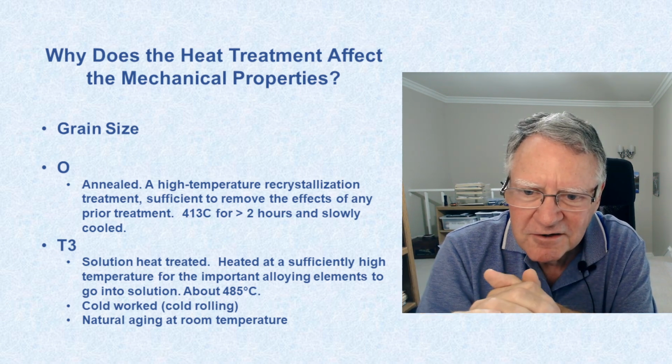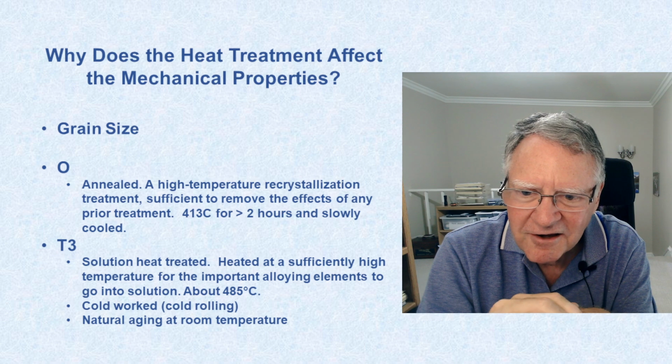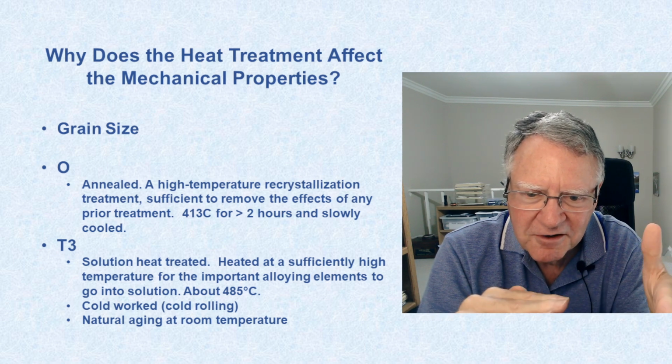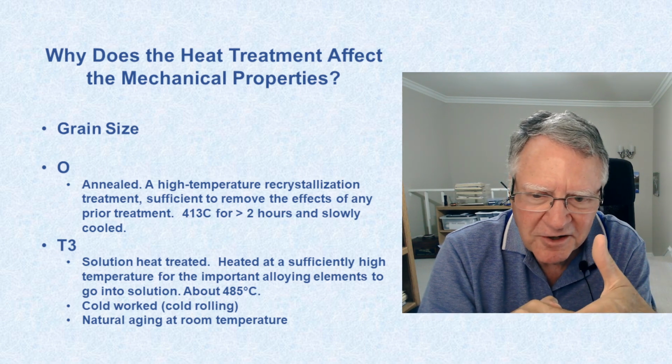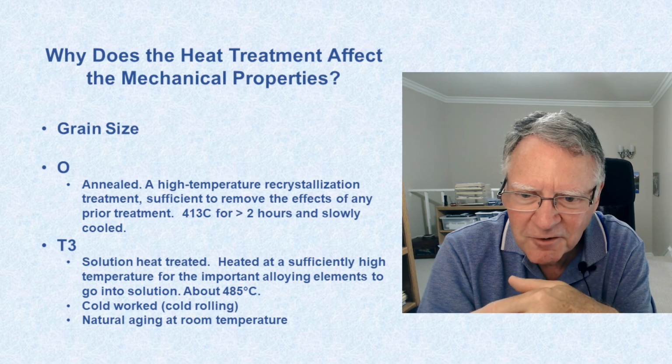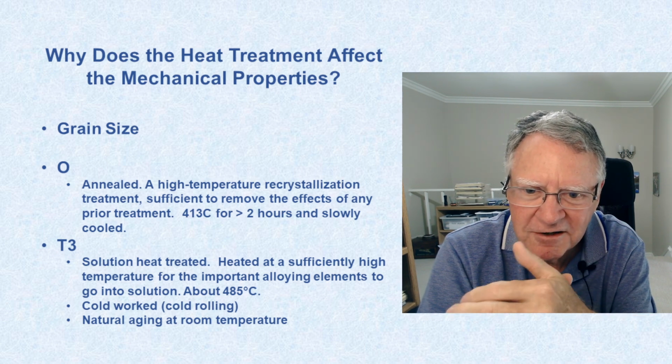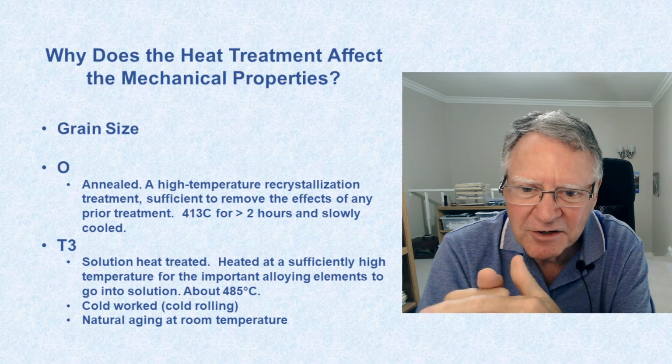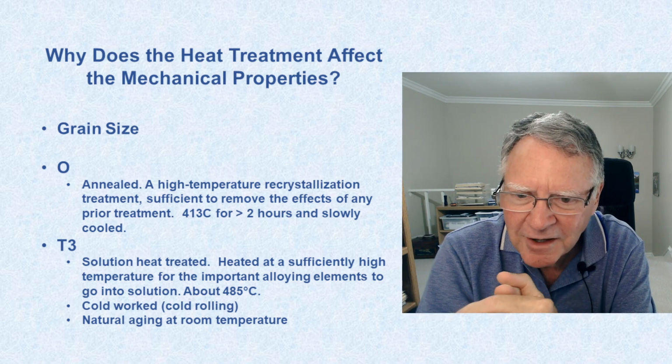So the slip and dislocation either has to just plow through a non-preferred orientation of this next grain, or it has to try and go around it or something.